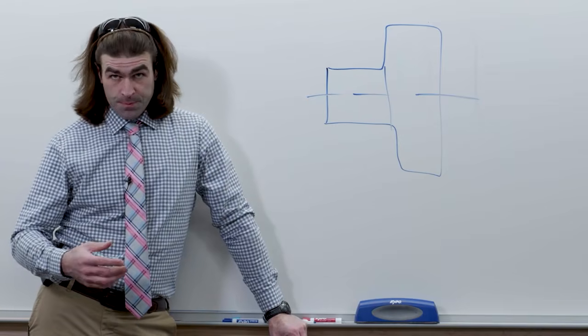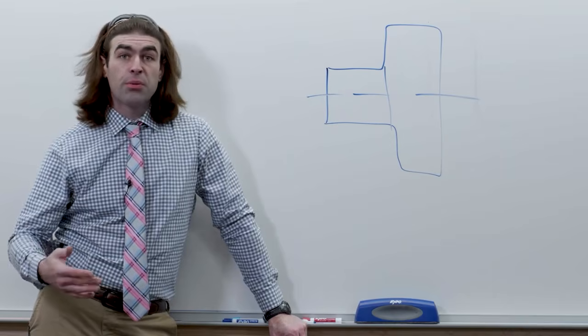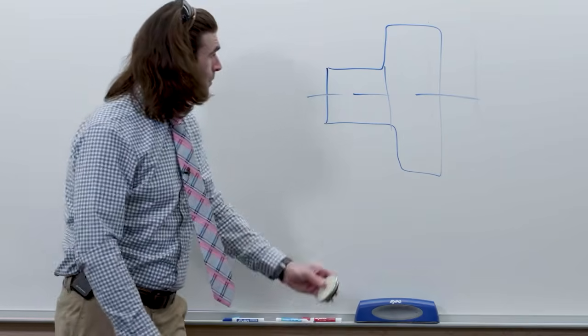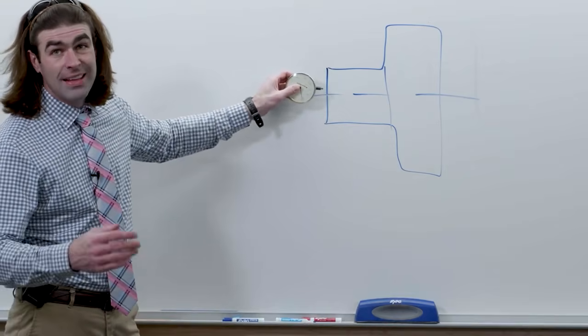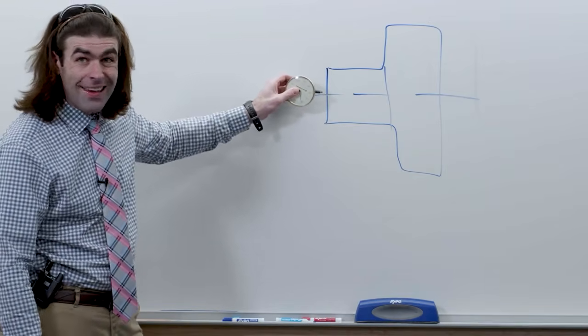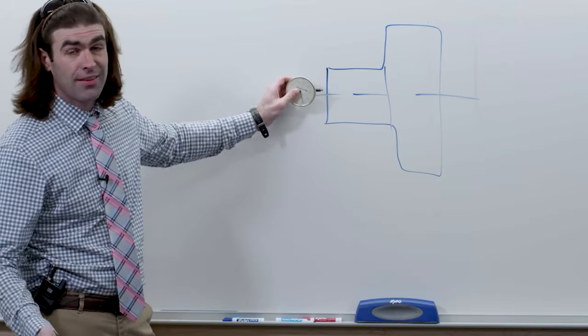What it does for a flat surface perpendicular to the datum axis, say we're checking this flat surface, it controls the flatness and perpendicularity to the datum axis.